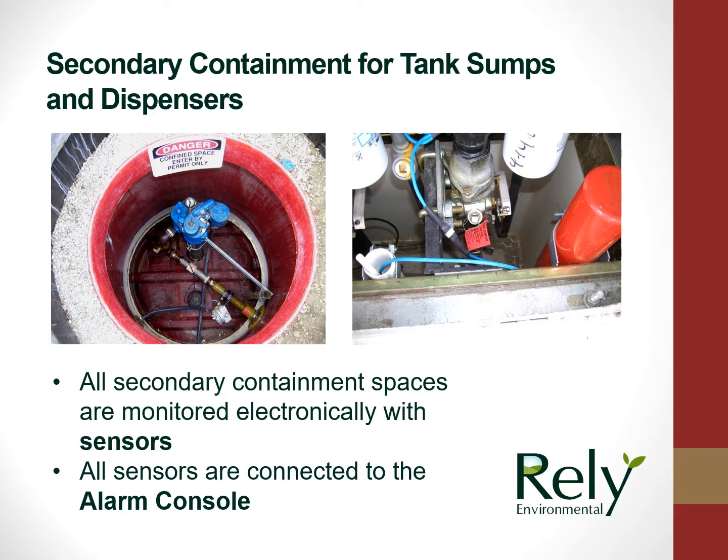All secondary containment spaces are monitored electronically with sensors that go into an alarm if they detect liquid. All sensors are connected to the alarm console, which displays a visual and audible alarm when a sensor is activated.